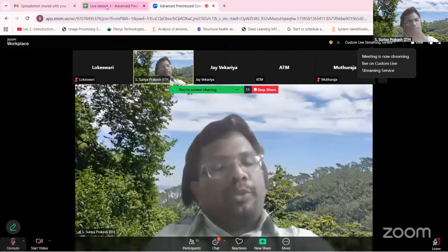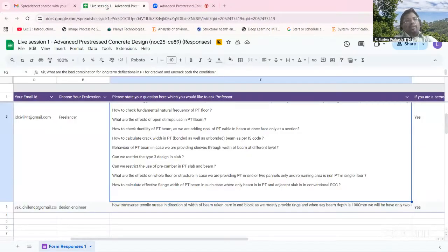So you do the same analysis, depending upon how much crack width you are allowing. This is from the design point of view, okay? When you are a design engineer, you know the exposure condition. Okay, I am allowing up to 0.2 millimeter. Then you assume that stress limit and find out what is the PT cable and the eccentricity that is required to meet those stress limits. That's point number 1. The second thing is, okay, now the section is already designed.